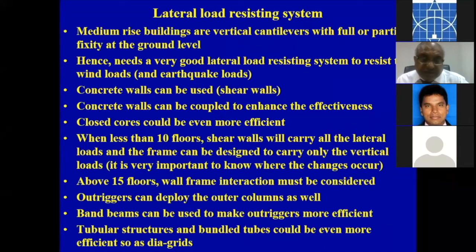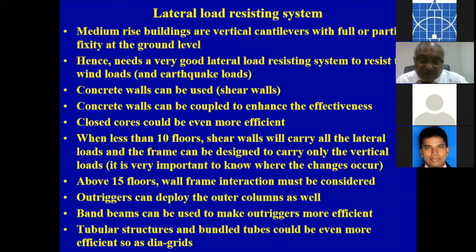The real reason is it is a failure of a key element. Key elements are the elements that are actually holding the structure together, and failure of any of those structural elements can mean the total collapse of the structure. And one of the key elements that could have easily collapsed in that particular building was the transfer plate. Why? Because it's so easy to under-design the transfer plate, or you can have a transfer plate where you have the same factor of safety as any other beam in the structure, which is wrong. Transfer beams are so important. If you have the same factor of safety as any other beam, then you are making a big mistake.